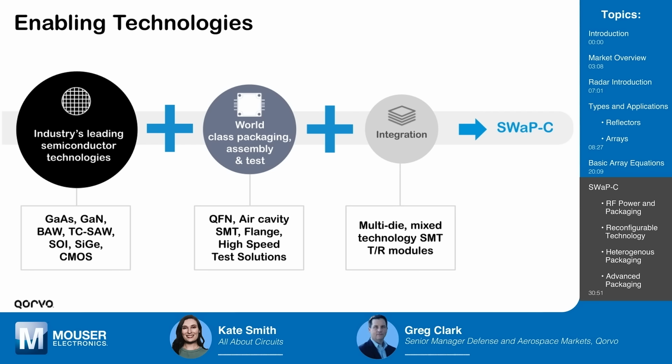There's more applications for the GaAs and GaN. I mean, the GaN's going to be your PA and maybe its driver, but the gallium arsenide, it's going to be everywhere. The SiGe or the SOI and CMOS definitely have their benefits that could replace the GaAs, but in my opinion, again, sheer performance, gallium arsenide and GaN are going to be your 1 and 2.